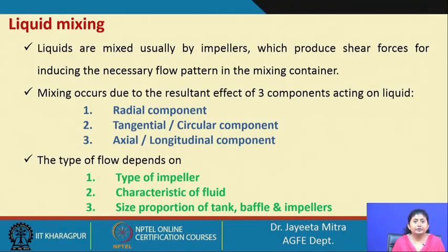So, suppose your impeller blade is not sufficient and it is only rotating the central part, and in the other part of the barrel the liquids are not initiated to flow. So, they will be untouched. Okay. So, the mixing will happen in the central zone only, in the bottom portion of the impeller, but it will not be uniform mixing.